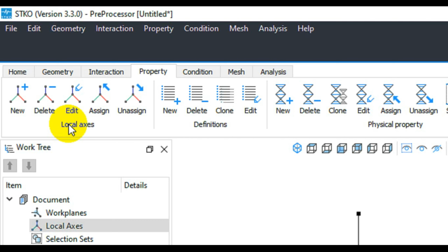For beam elements and special types of elements, the local coordinate system defines the orientation of the element's geometric and material properties. This is important for accurate representation of the behavior of the element, especially for anisotropic materials or elements with directional properties like beams and shells.